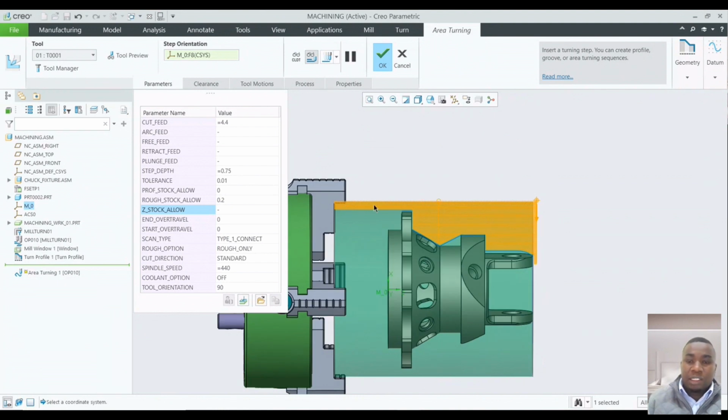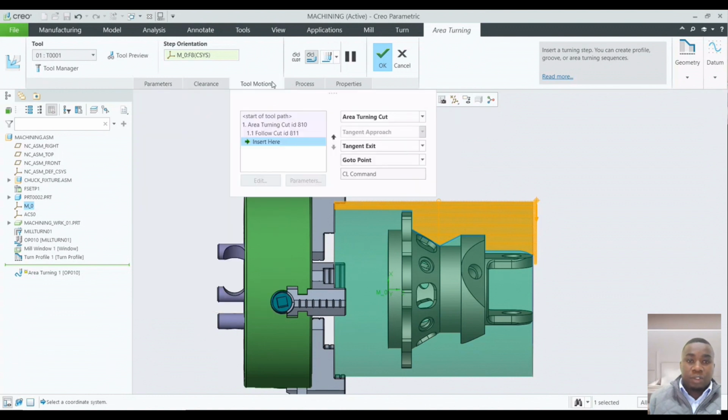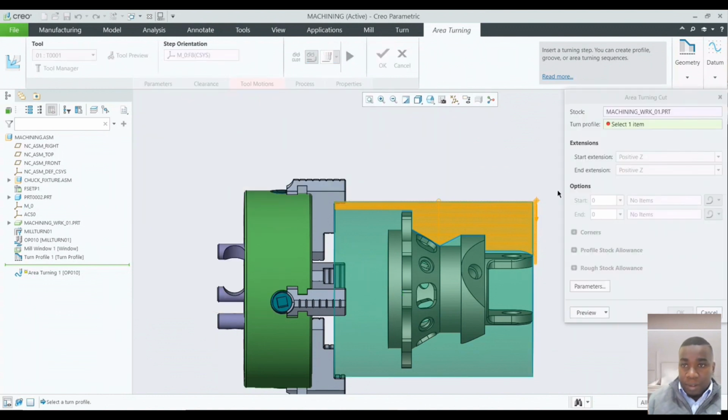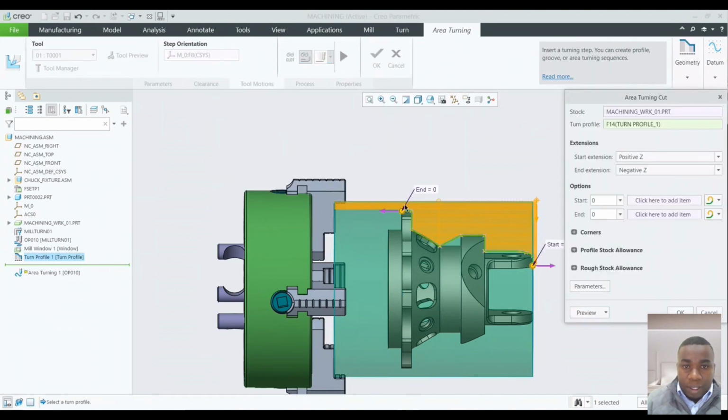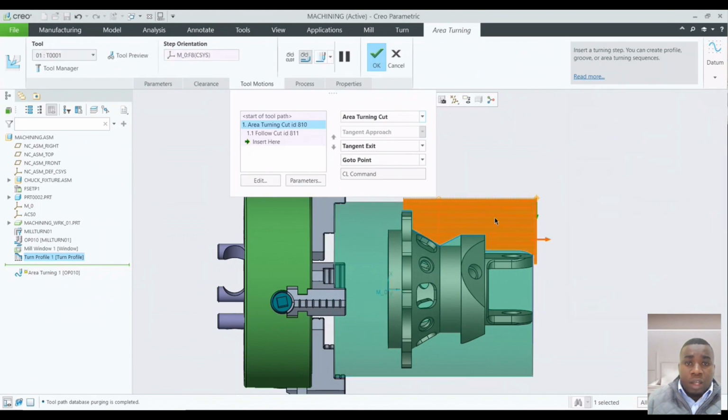So now we can say, okay, here there is a problem. It's going further than we wanted to. So I can always come here and just limit it so that it doesn't go further than where it is. And these are the options for the new lead out: the tangential, exit, and circular.